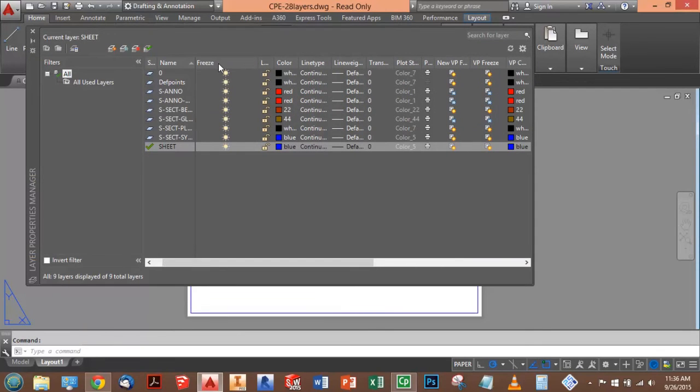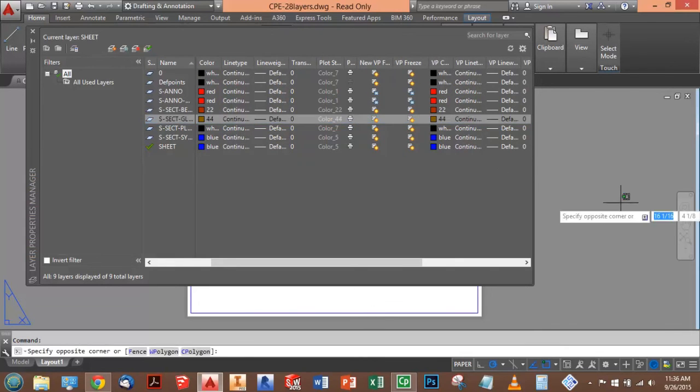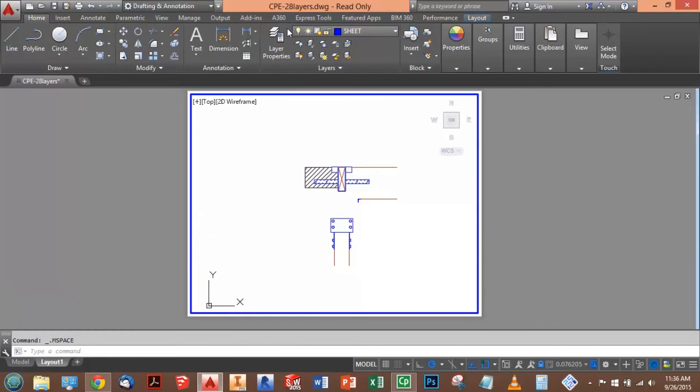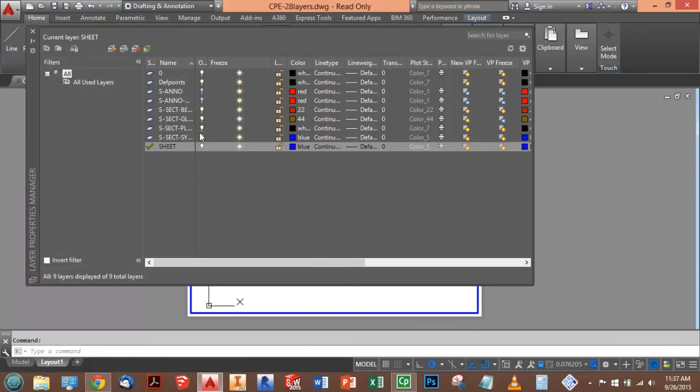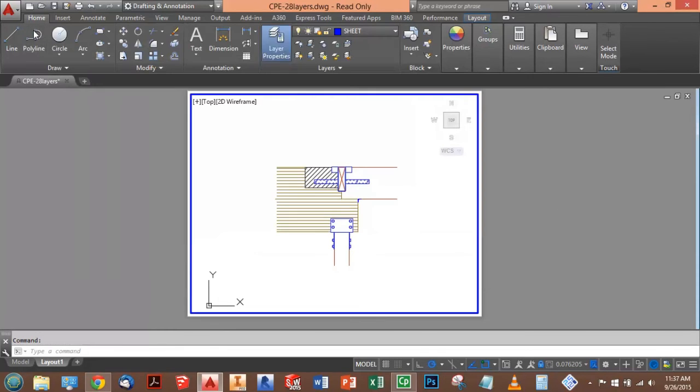you can set layers to be frozen in model space, or you can set them to be frozen just in a viewport. So here's my viewport freeze, and you can see that that same layer is frozen in my viewports, and that's why I can't see it. So if I turn it on in both of those places, and then let's type in REGEN, and this is being stubborn, so let's try it again one more time and turn everything on. So those are both on. Okay, and it didn't take that, so let's turn that on again